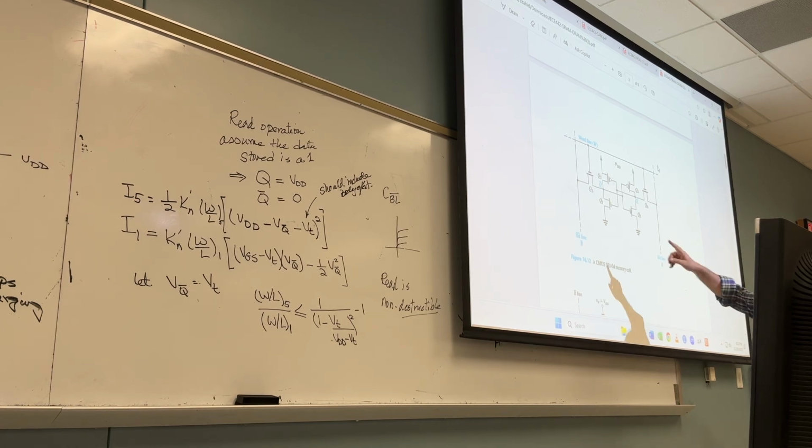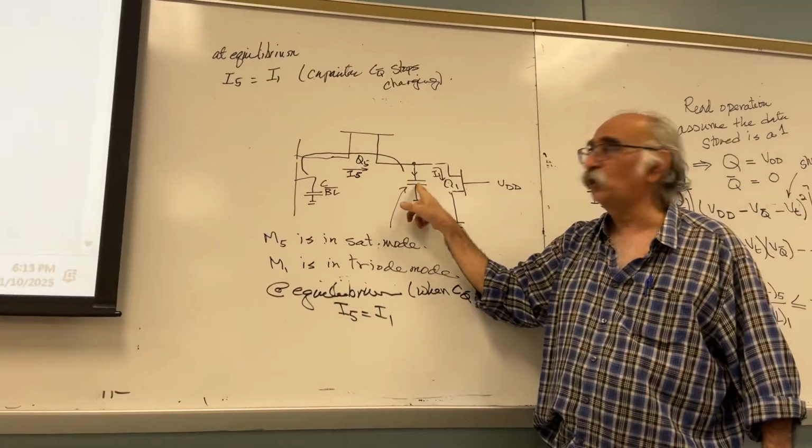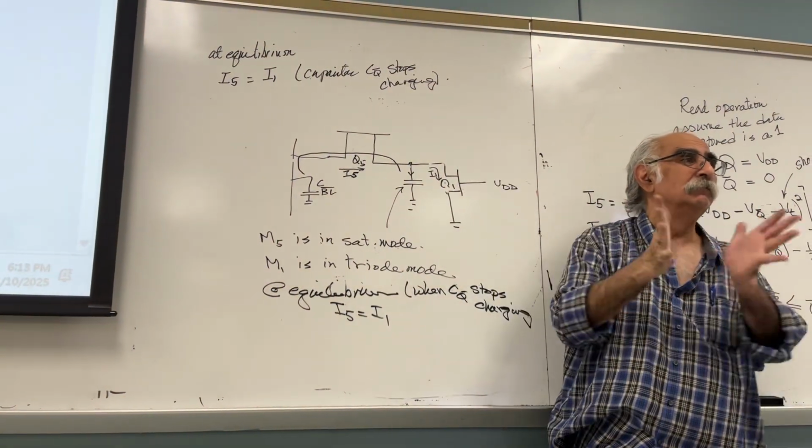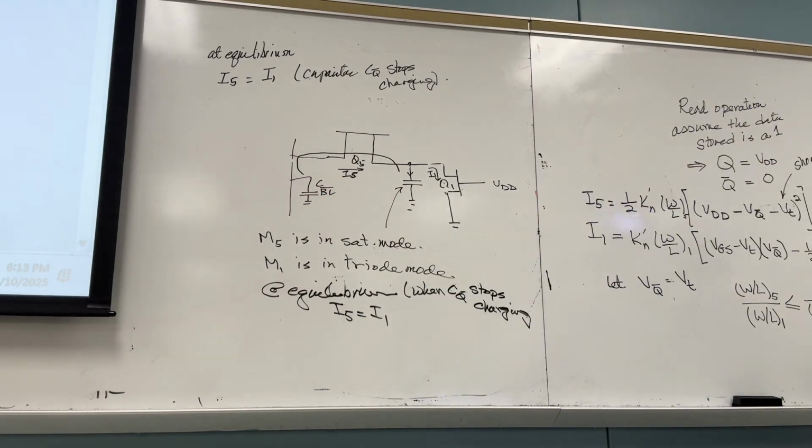Remember, by the way, this capacitor is much larger than this capacitor. Why? This capacitor is the result of all the cells in a given column, because they are all in parallel. And when you do have capacitors in parallel, the equivalent is more or less? More. Clear?